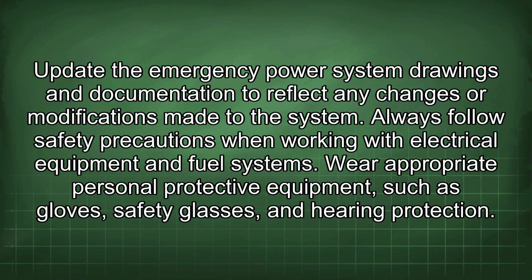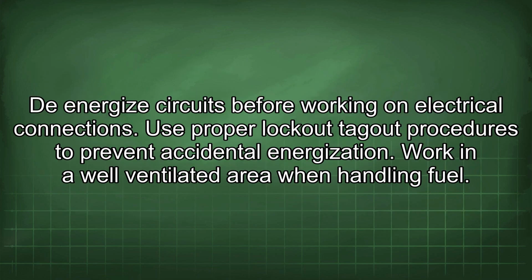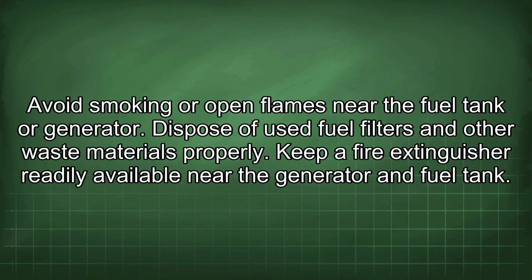Wear appropriate personal protective equipment such as gloves, safety glasses, and hearing protection. De-energize circuits before working on electrical connections. Use proper lockout-tagout procedures to prevent accidental energization. Work in a well-ventilated area when handling fuel. Avoid smoking or open flames near the fuel tank or generator.